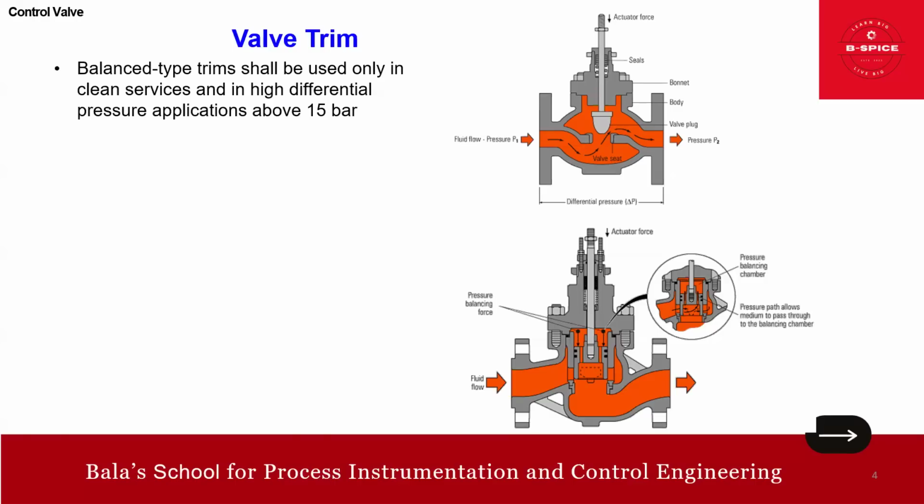Now, suitability. These valves are suitable for applications where the pressure difference is not large. That is the point. Another point: it may not handle a high pressure difference effectively. So that is about the unbalanced trim. Now coming back to the balanced trim.